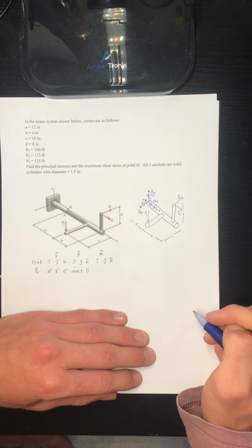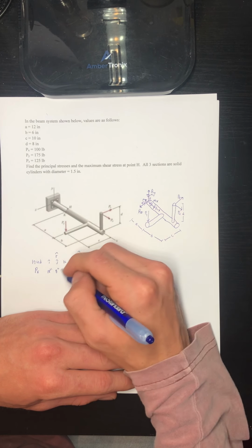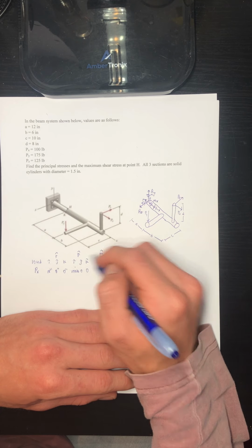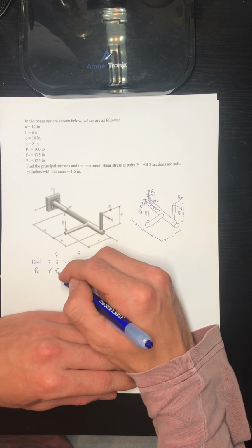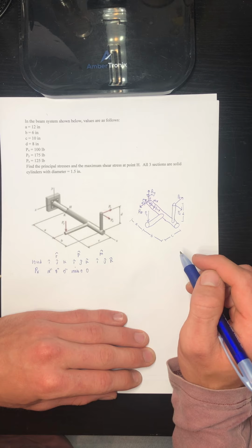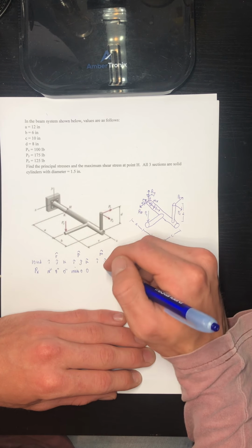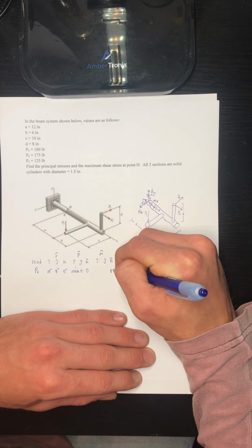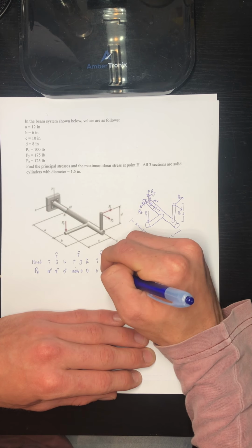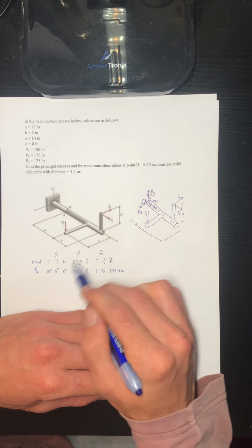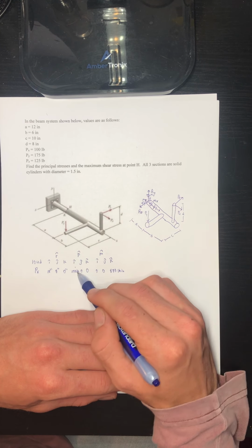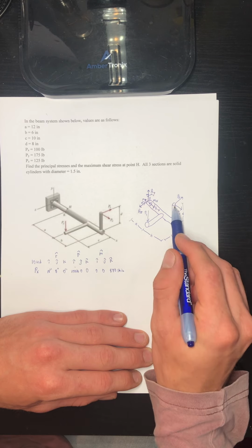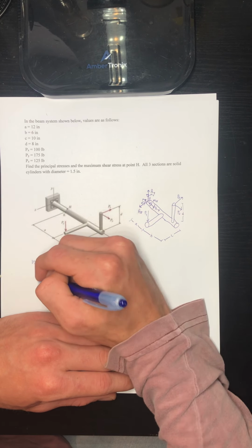0 in the Z. Now calculating our moments, perpendicular axes with an applied load creates no moment, but we can go ahead and get one resulting from this 8 inches in the Y direction. So we have 100 times 8 will give us 800 pound-inches in the Z direction. So this is all resulting from this PX here. There's that load in the X direction and the resulting moment from it being up on this little post here.